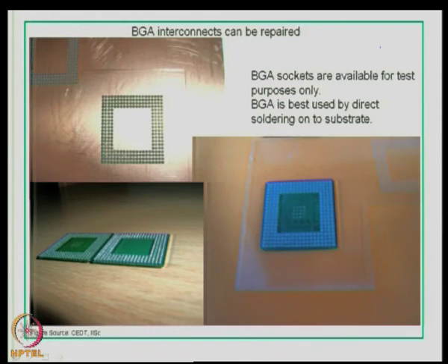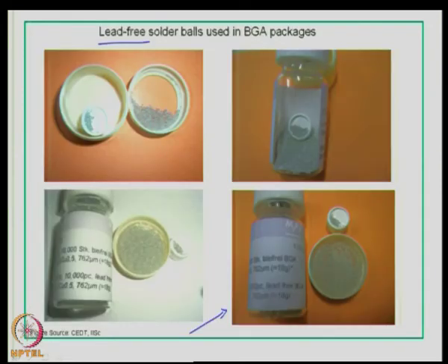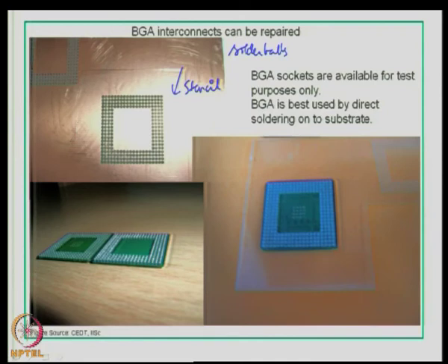If you look at this particular slide, here we have used another stencil, again pertaining to the arrangement of the BGA, and the distances are well measured. Here we have used solder balls itself. I have shown you the previous picture of a solder ball. These have been placed on these holes that have been drilled on a thin laminate structure or a thin polyester sheet, like here you can see here, which is used for alignment. And then once the solder balls have been placed, they undergo a reflow process. During the reflow process, the solder ball melts and gets attached to the pads on the substrate designated for these solder balls. So, the grid is established beautifully, and you can see there is no solder bridging at all. So, this is a BGA interconnect directly done onto an organic substrate or even a ceramic substrate.